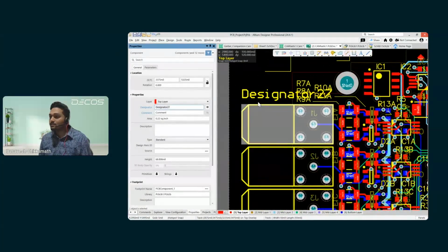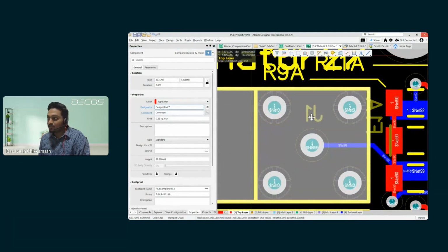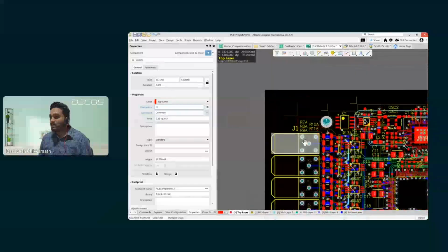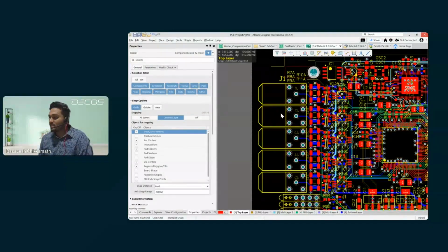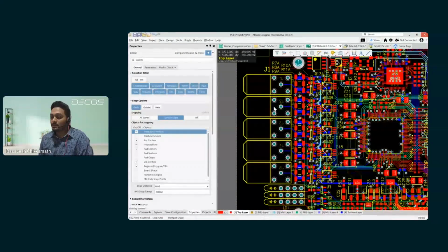Make sure you provide proper or matching reference designators when you're placing the components. The reference designator for this particular component was J1. So let me modify it as J1. Yes. So you'll be creating footprints for each and every component and you'll be replacing or adding them exactly on top of the existing free lines or free paths.